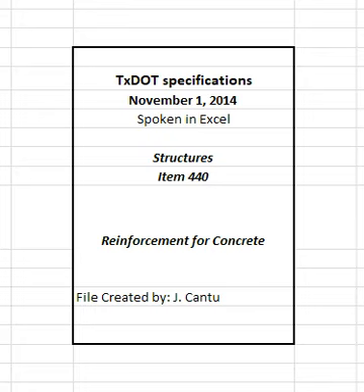Ensure welded splices conform to the requirements of the plans and of Item 448, Structural Field Welding. Field prepare ends of reinforcing bars if they will be butt welded. Delivered bars must be long enough to permit weld preparation. Install mechanical coupling devices in accordance with the manufacturer's recommendations at locations shown on the plans.